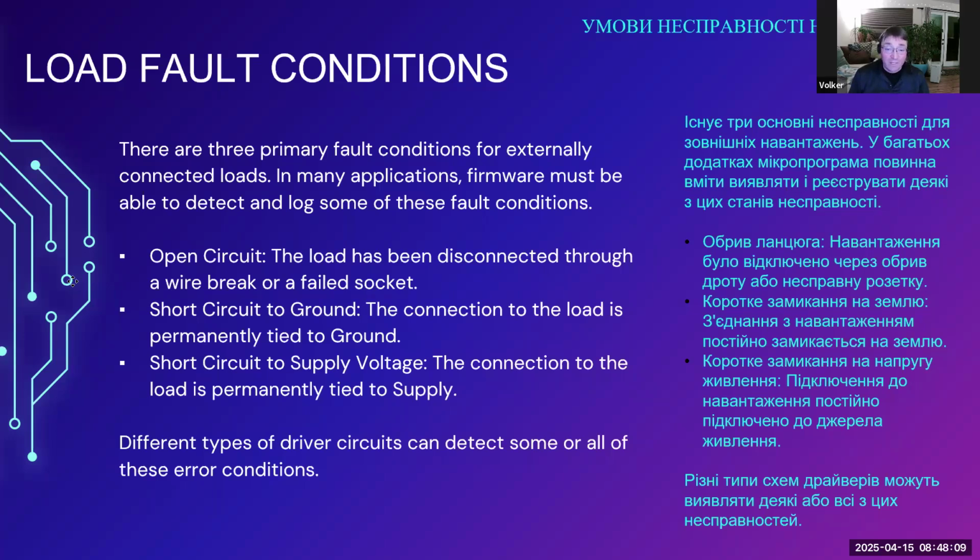In automotive applications, there are usually driver circuits capable of detecting a number of fault conditions, and the microcontroller or the processor in the engine control unit will check for these faults and, if necessary, log them for the mechanic to examine later.